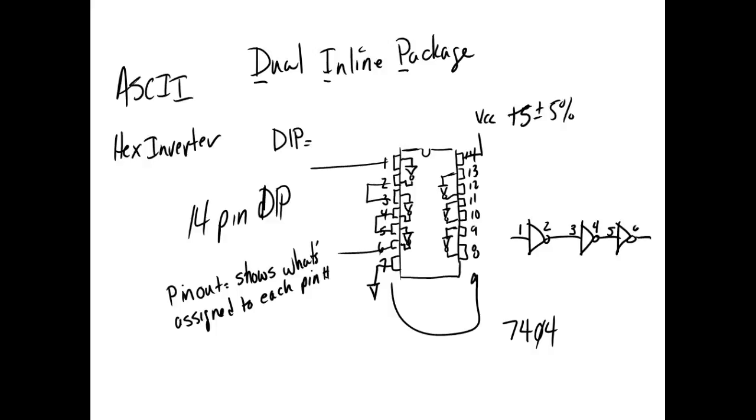But I guarantee I'm going to put on the test, how many inverters can I get in a 16-pin pack? And somebody's going to say 8. They're going to forget about what? You got to have power, and you got to have comm. You got to have power. These guys here don't work off nothing. So we sacrificed 2 pins, but look at the size of that thing.